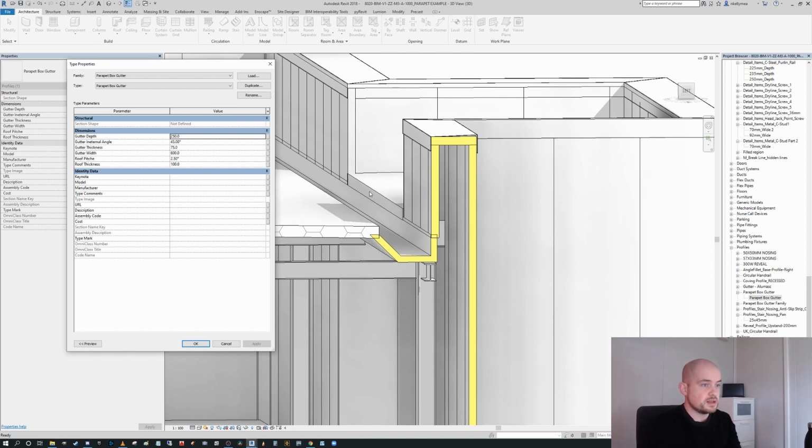Okay, so in this instance, I'm going to say I want the gutter thickness to be 90. I want the gutter depth to be, I think 250 looks like it's about right there. I'll give it 200. I want the gutter width to be, I think I measured this at 604, I think it's about 614. Our pitch in this instance, it shouldn't have an E there, mind you. I misspelled that. This is only a 1 degree pitch in this example, so I'm just going to say that. And our roof thickness, I think here, this leading edge here, is 138.